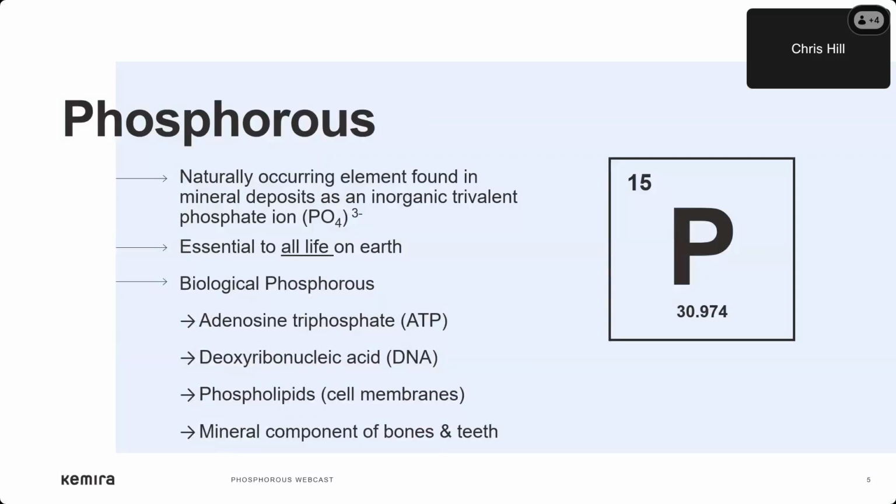Phosphorus can be found in the free state as PO4 3-, dissolved in water, often called orthophosphate, or in polymeric di, tri, and other condensed phosphate forms. It can also be organically bound as it is found in biological systems. Some of the biologically bound forms of phosphorus are listed here. Because biological systems are dependent on adequate phosphorus, when an excess of phosphorus is released into the environment from wastewater and agricultural sources, an overabundance of plant growth occurs, leading to problems in the ecosystem.